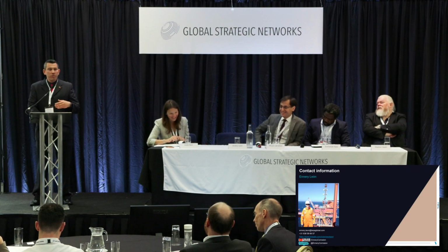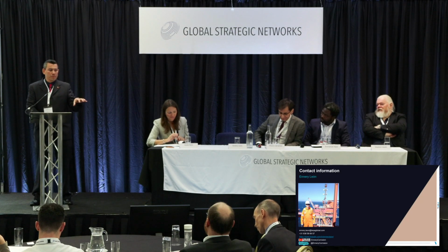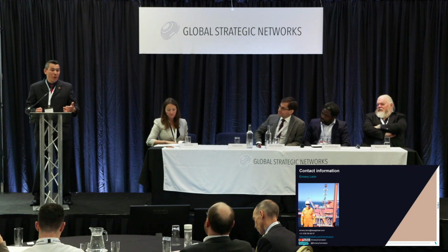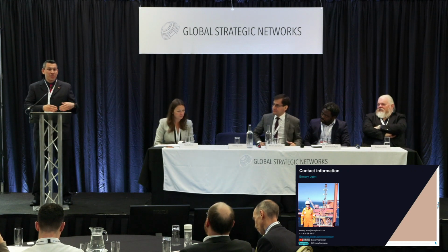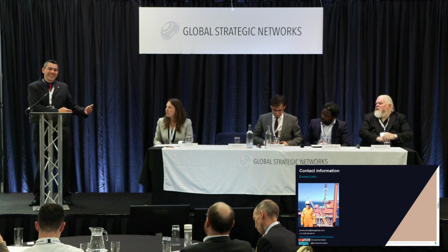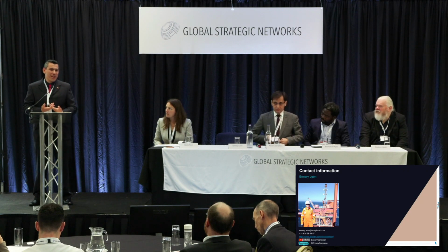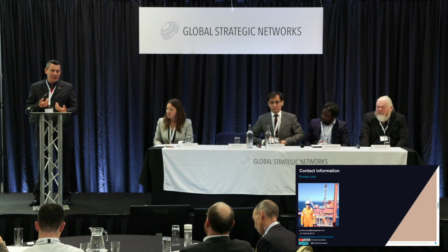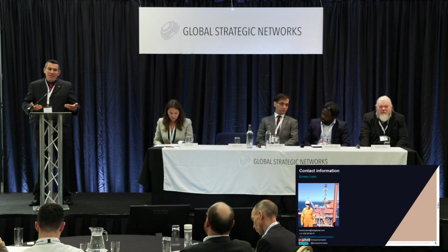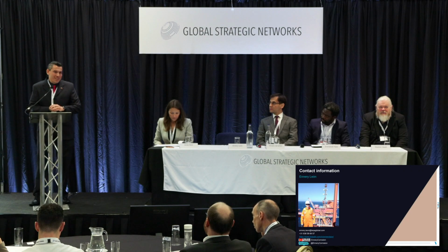And then if they need to check, for example, a corrosion inhibitor pump, it would take 2 or 3 weeks to repair because you have to create a work order, maybe a third party has to come on site. From the process point of view, you are interested in having a very quick reaction, but in reality, it's not going to be the case, so you need to find the balance. Does that clarify?